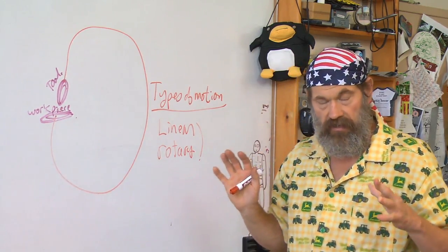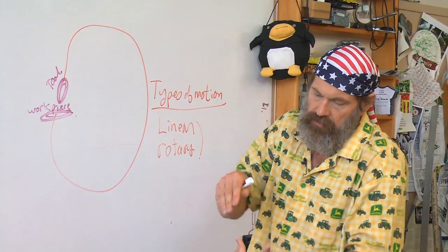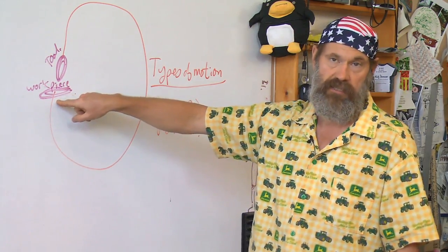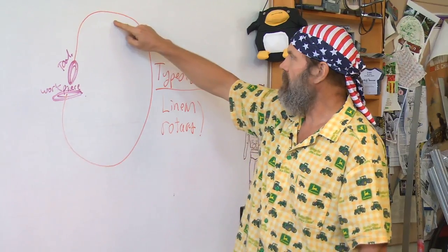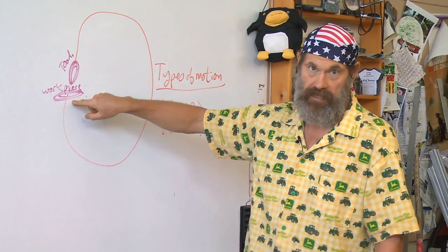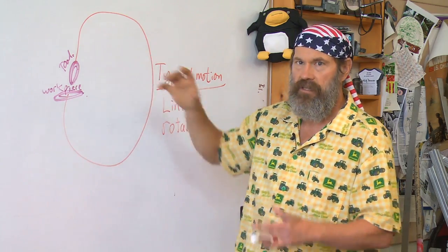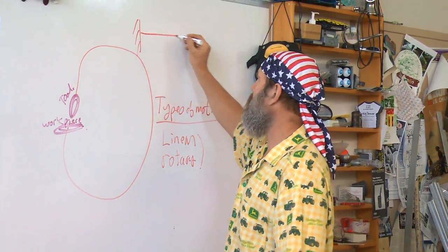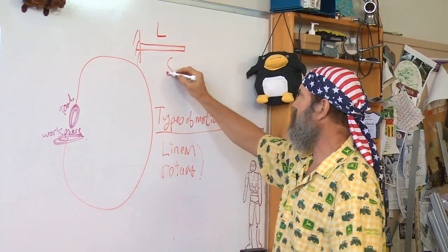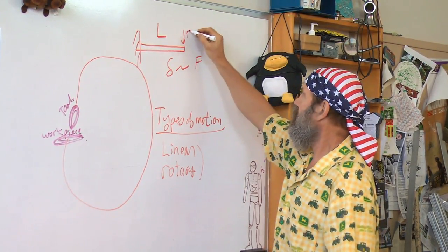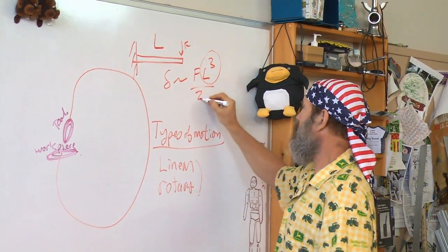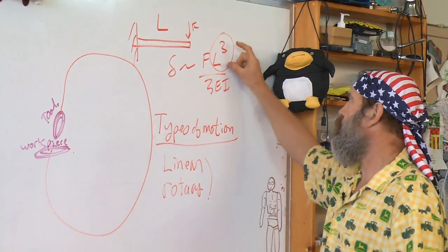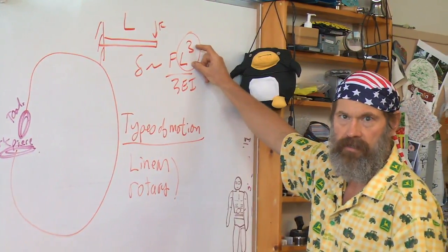Because remember from your knowledge of a structural loop, as the machine moves, you would like the shape of the structural loop to remain as constant as possible. You would like the length of the structural loop to be as small as possible. The smaller the structural loop is, the greater the potential stiffness of the machine. Remembering the lesson from a normal cantilever beam of length L, that the deflection goes like FL cubed over 3EI. So the structural loop length typically has a cubic effect on the stiffness of the machine.